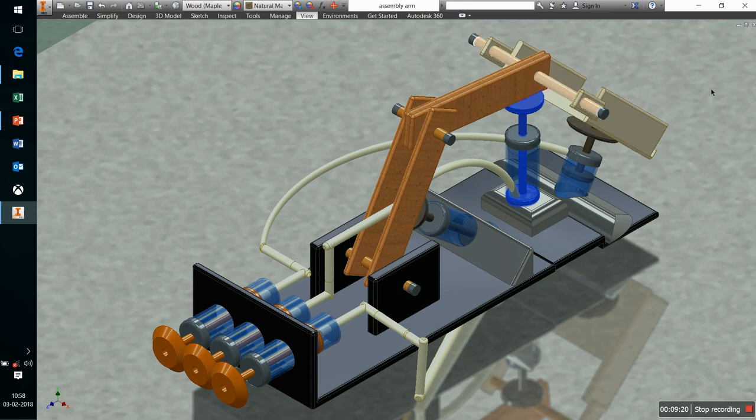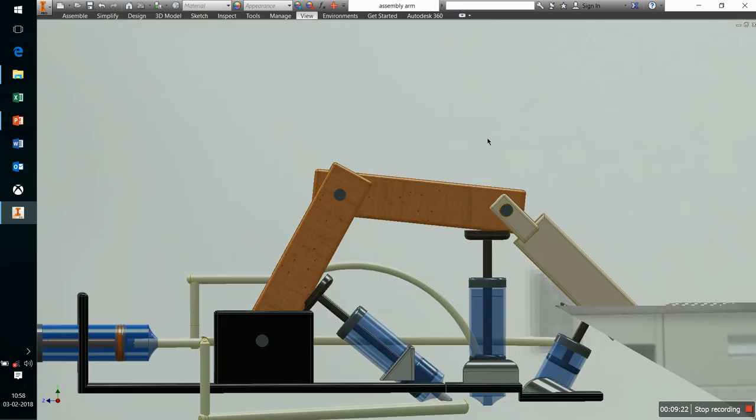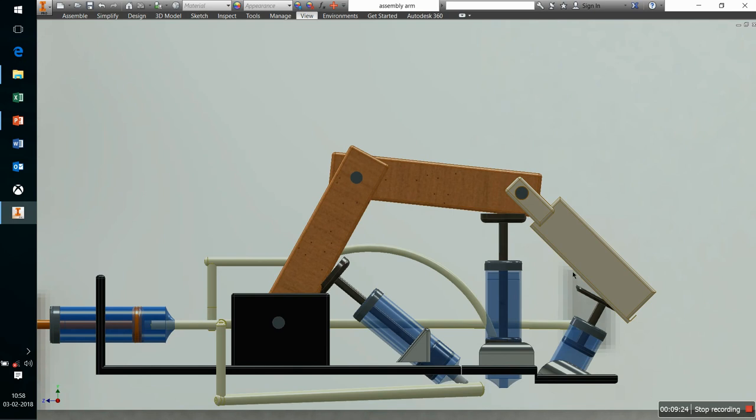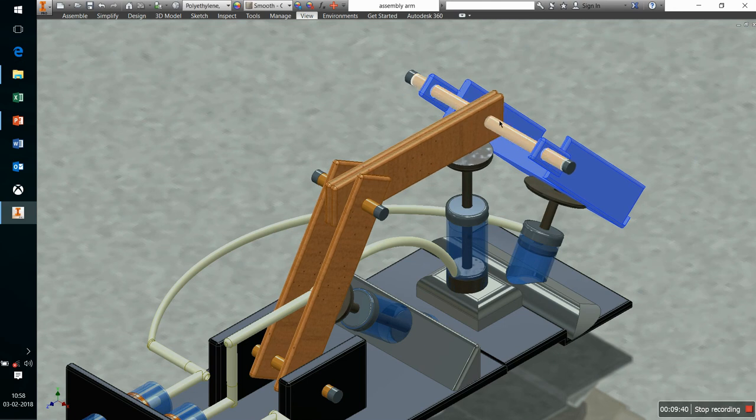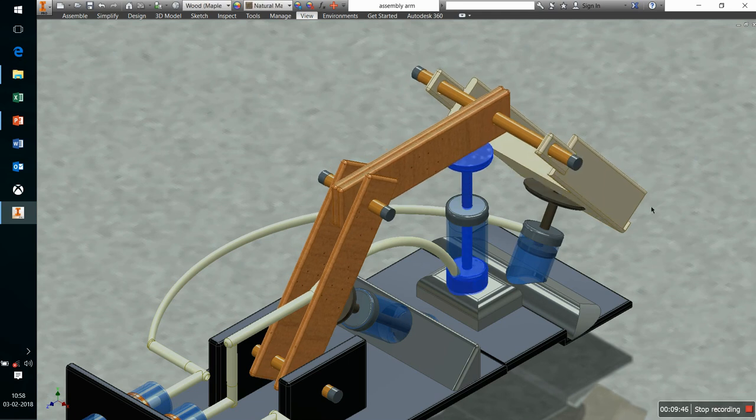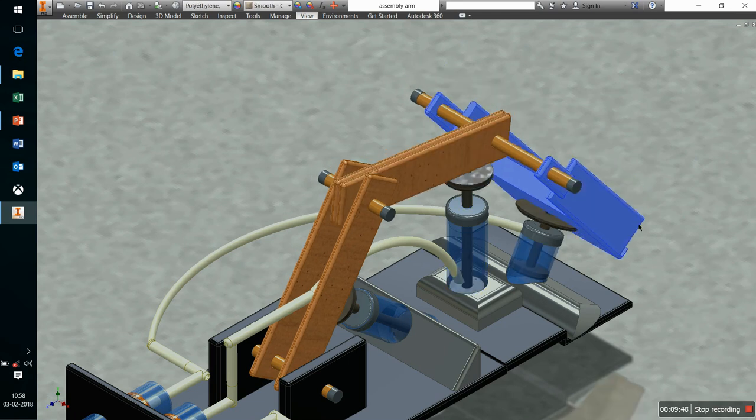Then you need to fabricate or design 3 arms, arm 1, arm 2, and arm 3, to move these arms using the piston cylinder arrangement. These arms must be joined via insert joints, so that they are free to rotate over these axes, and they are in turn moved by these piston cylinder arrangements.